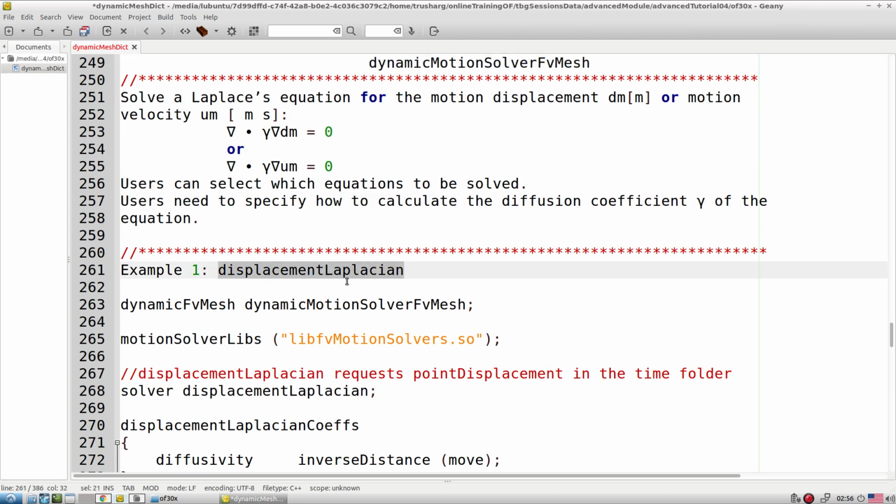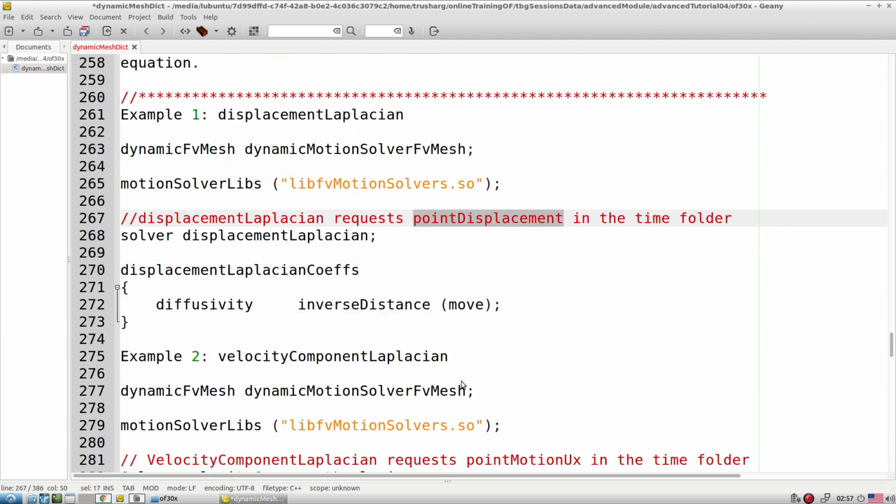When we talk about the displacement velocity, what it is going to do is look at how the mesh motion is displaced with the help of these displacement options. So it is called displacement velocity based, and for that a different file is supposed to be there inside the time folder, like the point displacement file, which we have to keep inside the 0 folder. Based on this point displacement we specify the displacement options. Whether the patch is rotating, moving, whatever we want, we have to specify in the point displacement file, and keep that file inside the time folder.